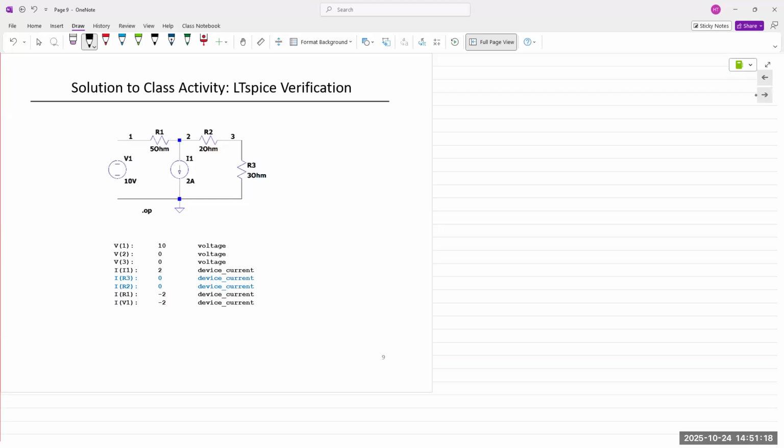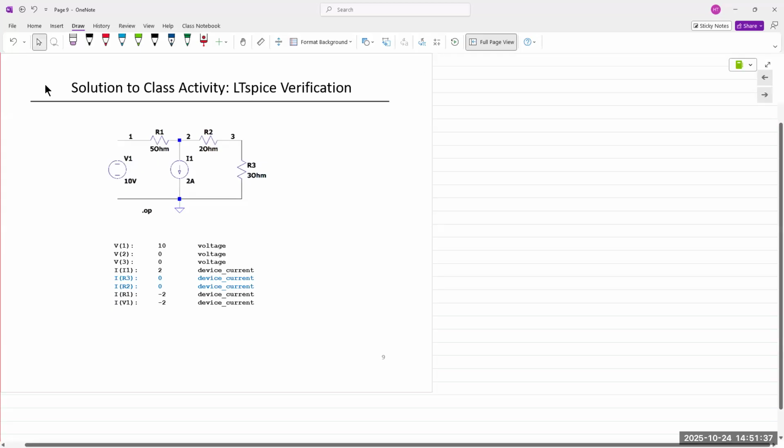One of the applications we saw was voltage division. We can obtain different source voltages from a single source. In the previous couple of slides, we had a source of 9 volts, but we derived a 5-volt source from it. That's an application of resistive networks.